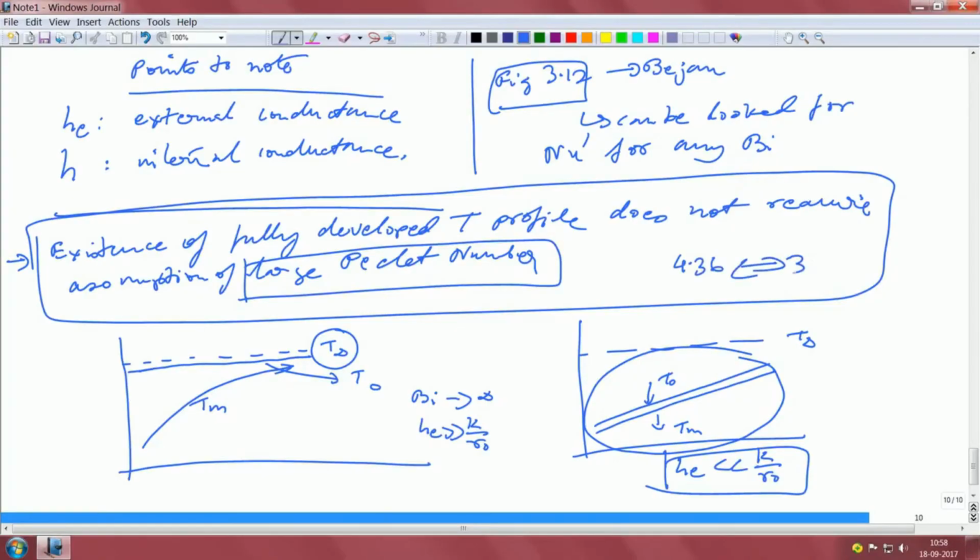We will also share that figure with you in the next class. We will start there, and also show you the Nusselt numbers for the different configurations, that means the cross sections. Those are mainly for handbook purposes, because actually solving this equation requires a little bit of effort, but you can still take a quick look. All we can say is that it varies from 0.436 to 3.66. That is the limit of variation of the duct side Nusselt number. It will always remain within these two bounds.